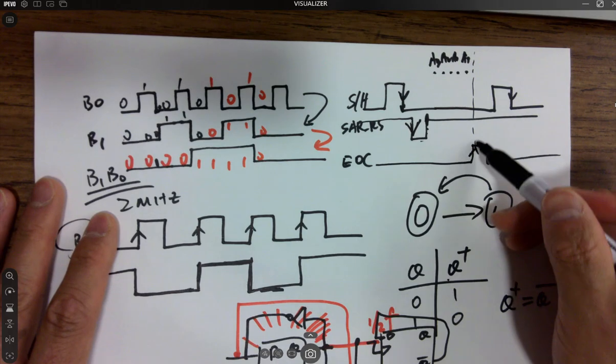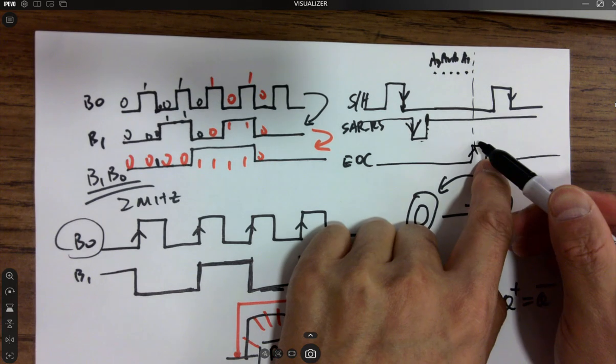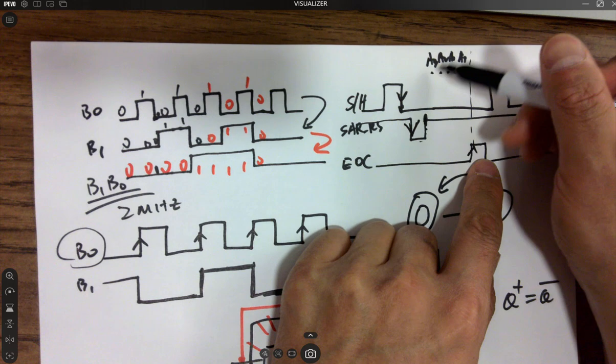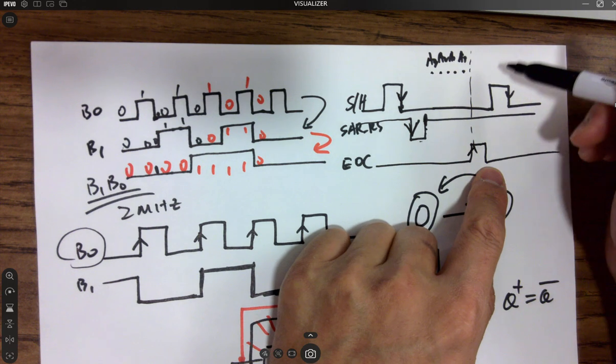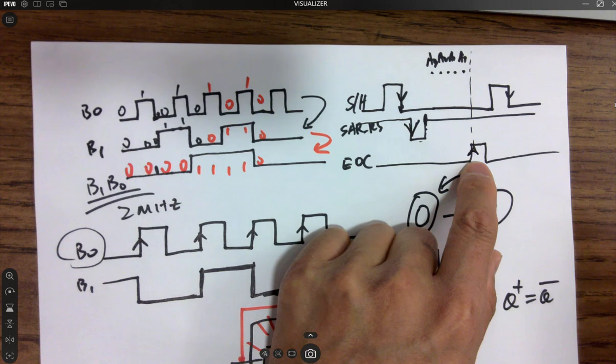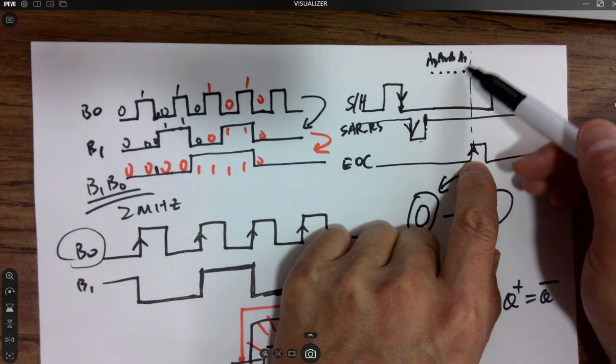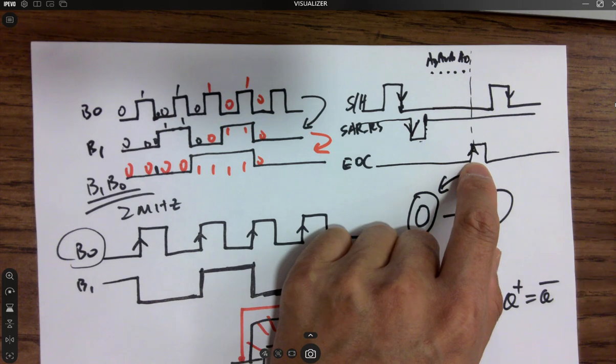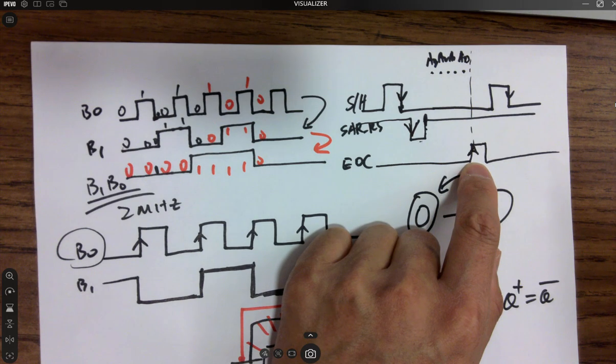And after that kick, if the data changes, because your SAR's clock is always pumping, it may change the result a little bit or may not. Doesn't matter because it only happens at the rising edge. We just need to make sure that after this, all the A's are ready, so we just kick it out. Then it's getting latched. We worry less about other things.